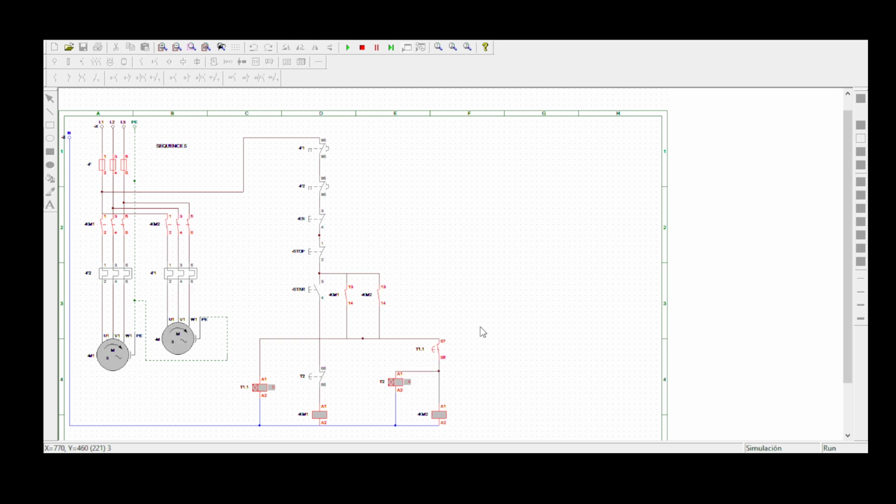Okay, here we go. So now we saw motor 2 is now rotating, and the coil also is energized. But remember, timer 2 is also energized. So timer 2 and KM2 energize at the same time. After timer 2 finishes counting, we must have a normally open contact here so that motor 1 can stop rotating. And that's it. We've seen motor 1 has stopped rotating, and motor 2 is continuing to run. So we've done what the statement required us to do.